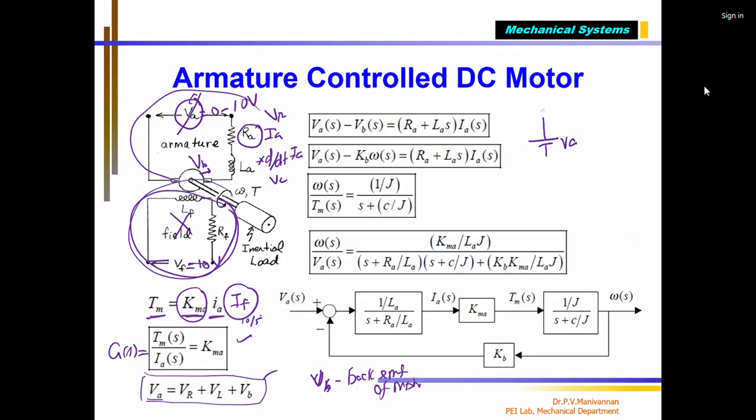So that means, being a constant, I'm talking about armature control, controlling motor speed by varying the voltage. If armature voltage becomes 0, even if the other value equals infinity, this becomes 0, and torque becomes 0 automatically. So that's why I'm controlling. But we are not going to have an infinite amount of current. The field coil is also limited, for example, 10 amps or 5 amps, whatever it may be.